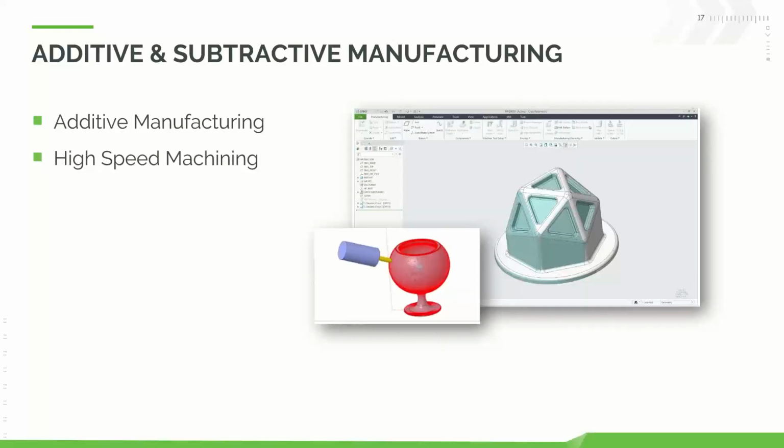Several different improvements in high-speed machining. That means better surface finish and flexibility with a new geodesic 5-axis finishing tool path. It helps in a lot of different areas, helps to improve tool life, avoid chatter, faster overall machining, and at the end of the day, faster overall NC programming time as well. So that's a big improvement that we have there, being able to do those faster and still end up with a better tool path.